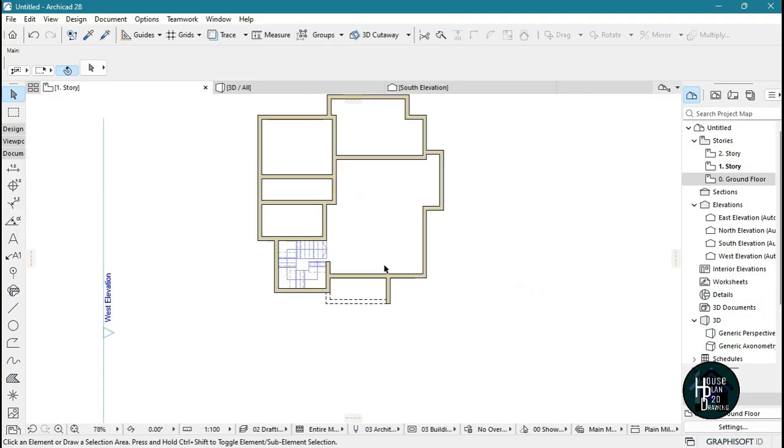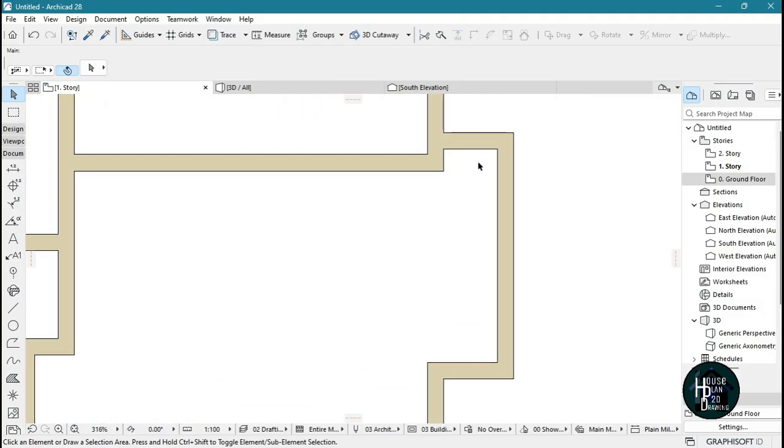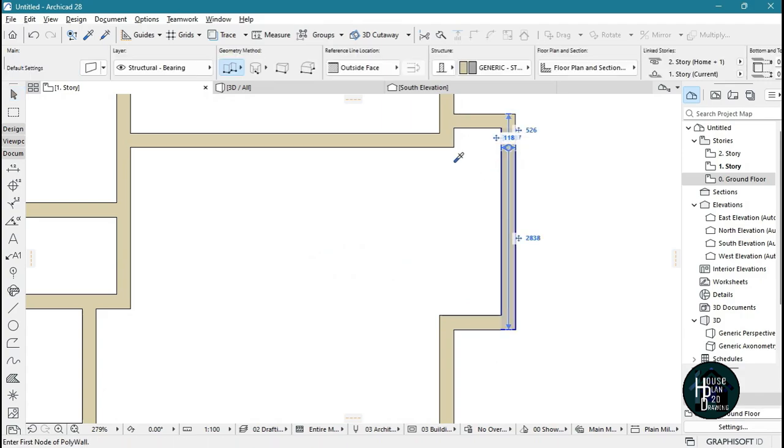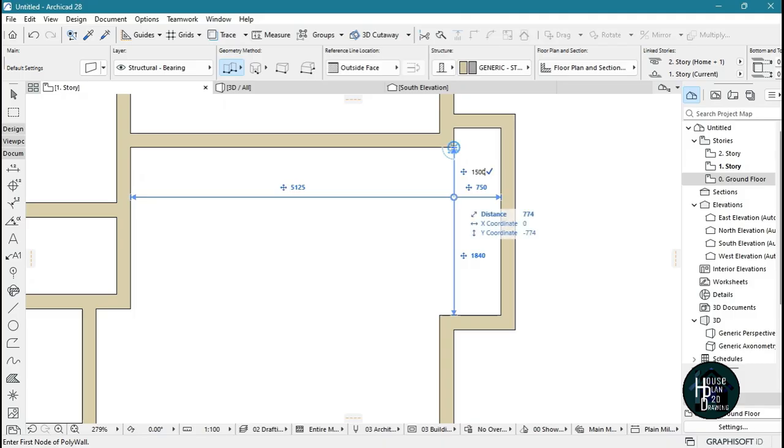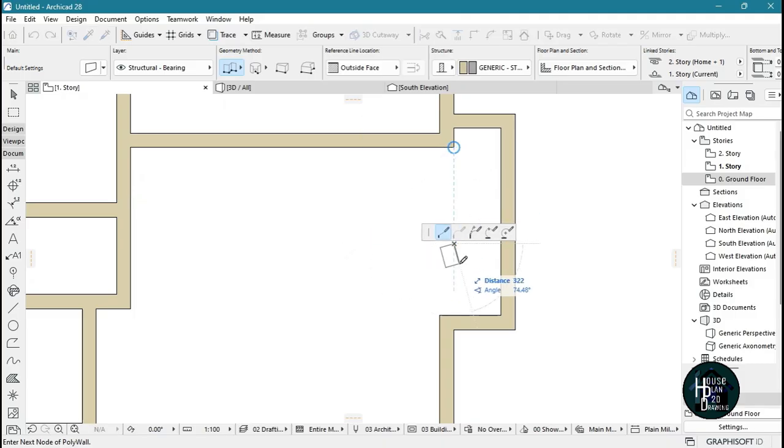Once you've done this, what I want us to do is come to this side here. Hold down Alt, select this side here, put the cursor here to this edge, allow it to load up, and let's give a distance of 15. Click enter, and once you click enter, stretch it to this side here, double click on it.